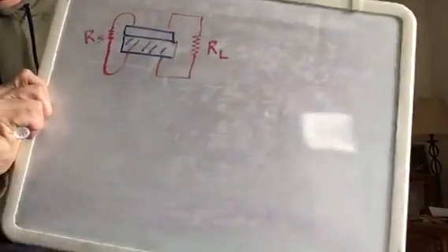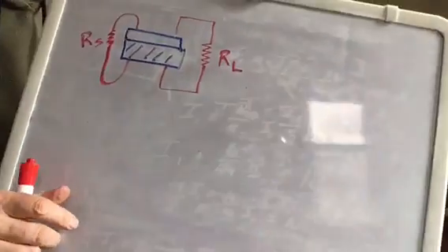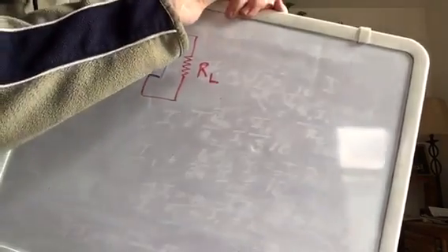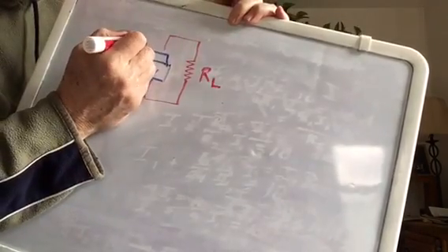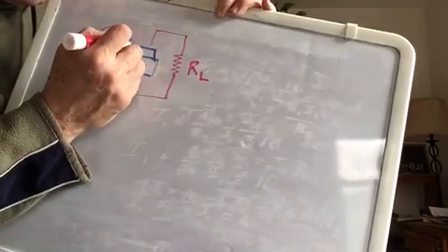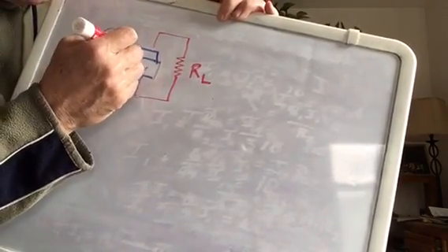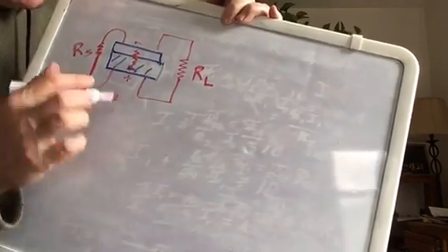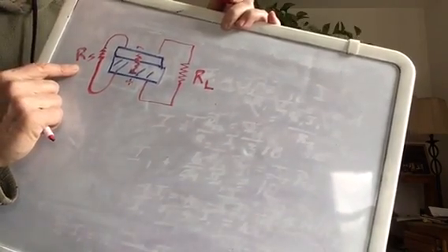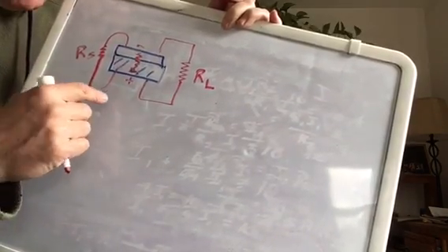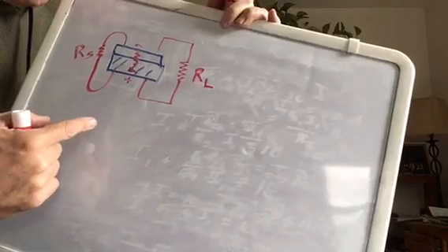All right, so drawing similar to what's in the book, but with a little bit of variance, and certainly similar to what we had on the test, where we can have current go through this load, but there's actually a way for this charge, let's take a look at one particular charge element, and there'd be a corresponding plus down below, there's actually a way for that current to go through the PV cell and go that way. And that's resisted by what's sometimes called the shunt resistance. So there's 2 different paths, and if you think about it, those paths are in parallel.